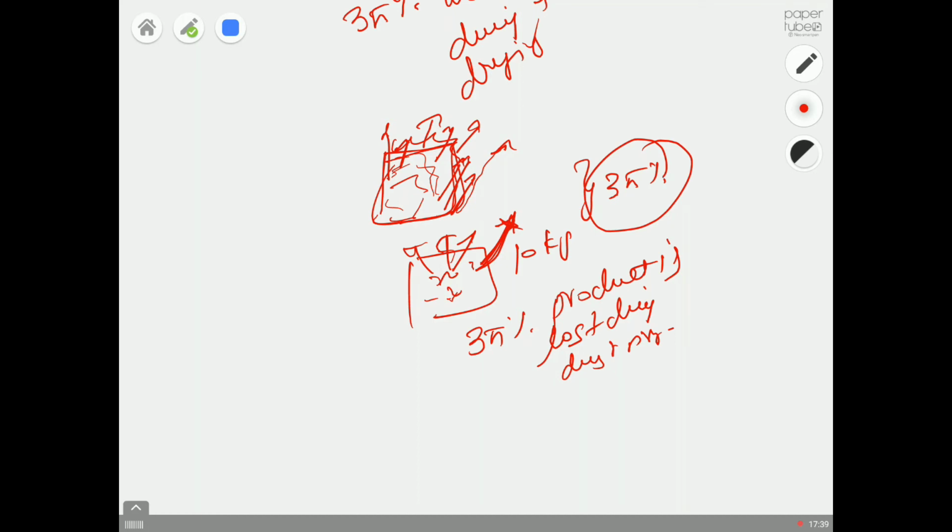So these are not my assumptions, these are something they state in the tutorial book, so I try to keep with those numbers. If you want we can even change it, why not 25% or 10%. So what that means is we have roughly 10% of soluble components in your product that will be soluble in your heptane and then evaporate with your solvent during the drying process. So that's the meaning of this.